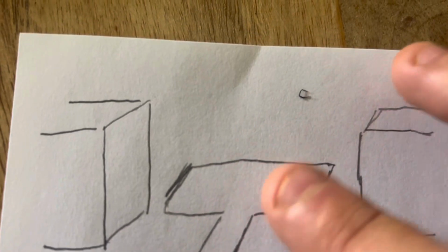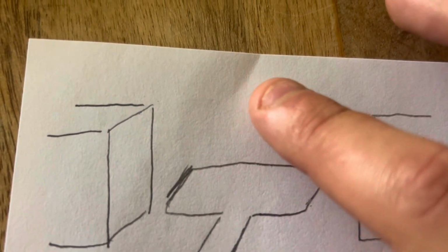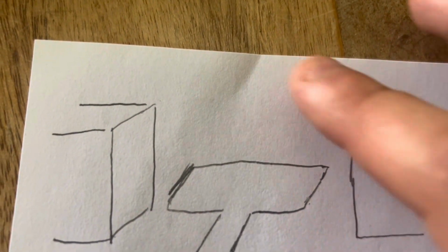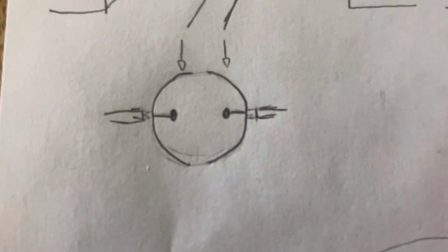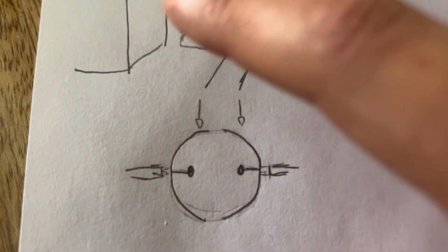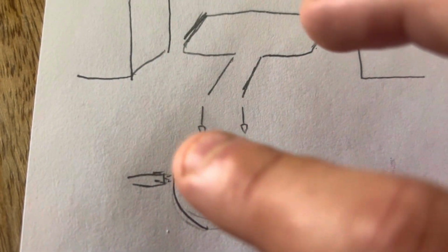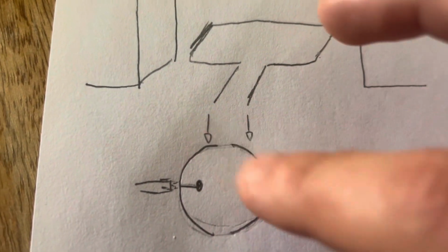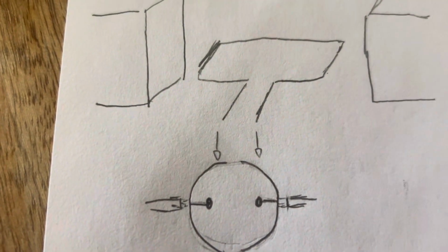So if we have that same setup, we need a way to switch the current so that this switches, rather than going up, to going down, or vice versa, whichever way it's spinning. Now the way you do it is you have two brushes connecting the current, so it would go in this way, and then it would go around the armature and out this way. And then as soon as it gets vertical, there's a little gap here that would switch the direction of the current so that it keeps spinning.